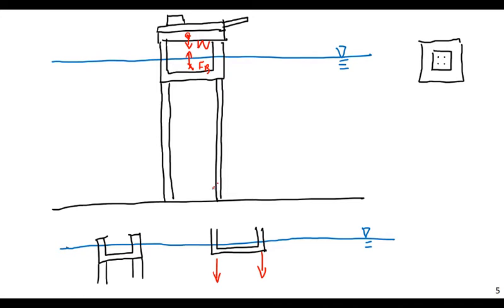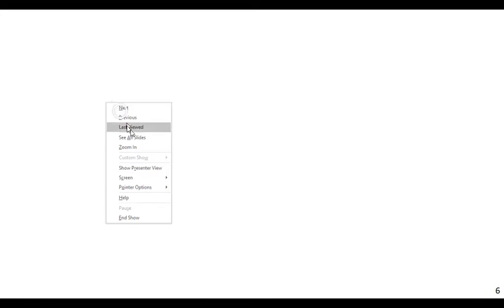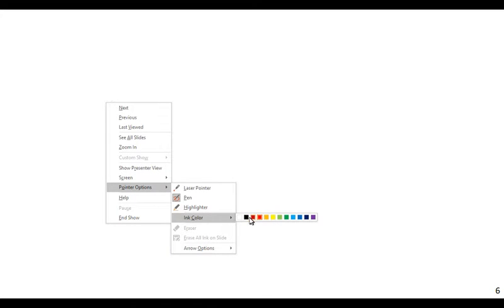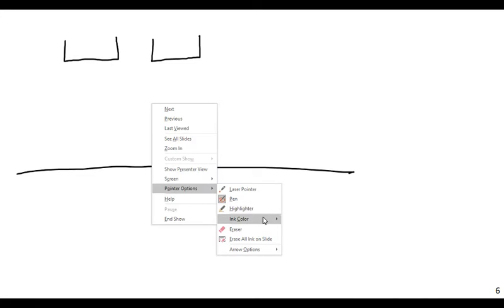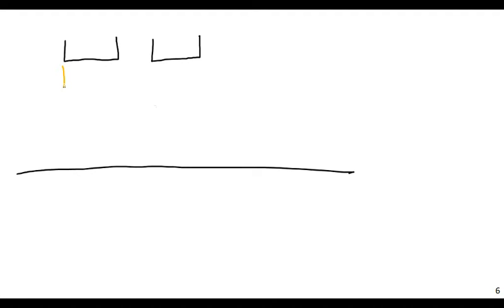But anyway, so you get the tendons to generate this enormous tensile force. And then suddenly, now we actually have a way of making this previously unstable structure now stable. So again, the tendons are generating, there's the hull. And look, I'm going to show what happens when this thing becomes displaced. So the tendons are normally vertical, and I'm definitely going to exaggerate the deformation. But initially they're vertical, and they're still generating a force, but it's a purely vertical force. The buoyancy is being resisted by tension.